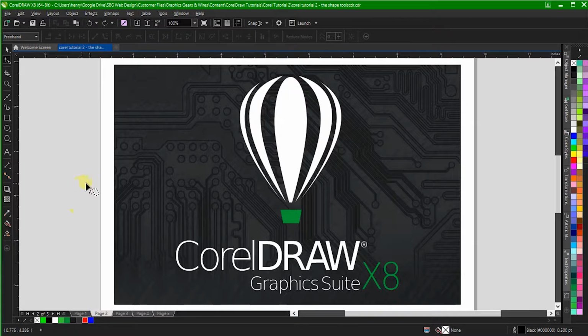You can select an object using the shape tool. Notice how this selection is different from when you used the pick tool in a previous lesson. There is no center point or control handles in this selection, only a marquee around the object outline and these open square points around the outside. These points are called nodes. Nodes are used to control the shape of an object in CorelDRAW.